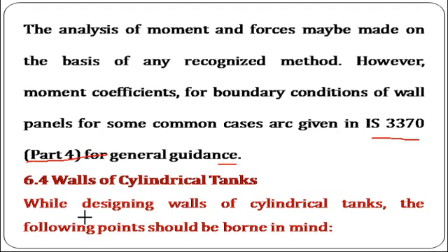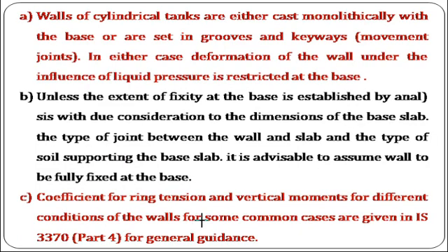Then clause 6.4 refers to the walls of cylindrical tanks. While designing the wall of a cylindrical tank, different points should be borne in mind. The walls of cylindrical tanks are either cast monolithically with the base or are set in grooves and keyways, that is, the movement joint that we have to provide.